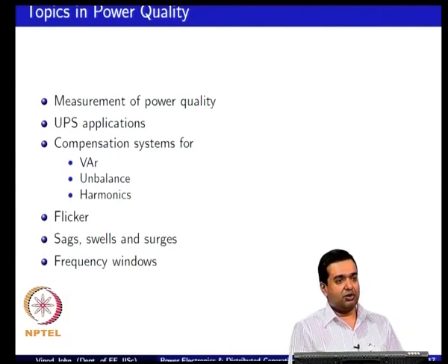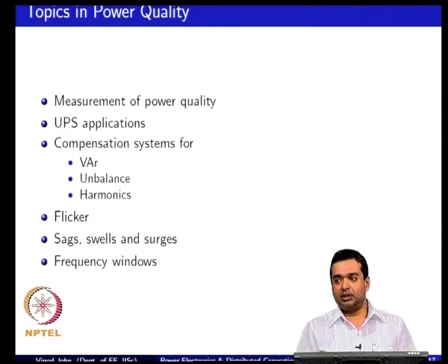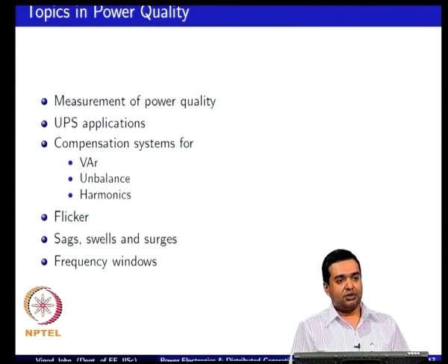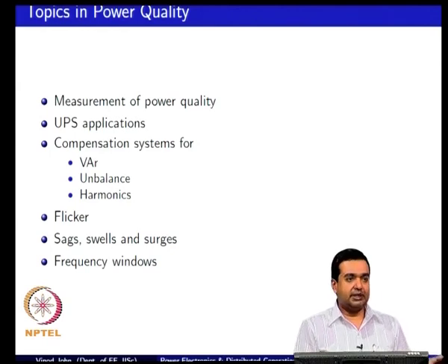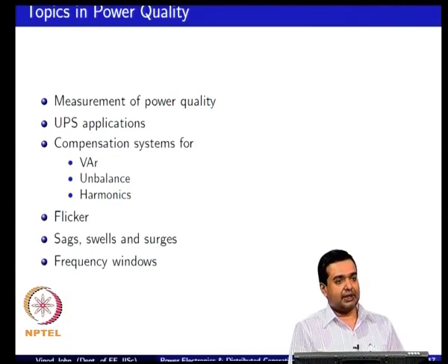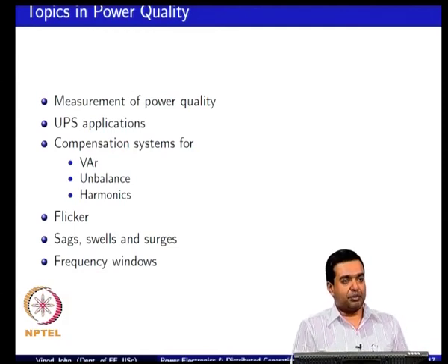A customer side power quality issue is a power cut or an outage, whereas you can also have power quality issues from the provider side, where a customer load is drawing a lot of harmonics, or a customer load is highly unbalanced. So, it is a power quality issue which is impacting the provider. Power quality is not just a one sided issue. You have to look at it from both sides, from both the loads and the sources, and ensure that overall the system is in good shape.